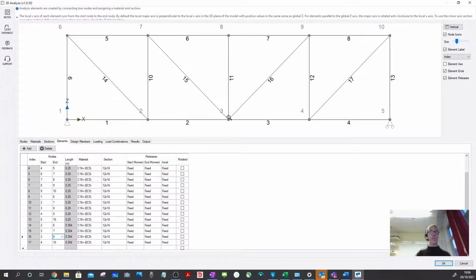We're not quite finished yet. If I was to make this into a truss, it would be very difficult for me to make element number 9 connected to number 1, 14 and 5, all with moment connections. So if I'm going to assume that they're pinned connections just now, it's rather easy for me to do that.